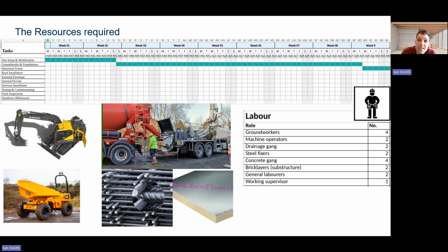The second resource is our concrete and reinforcement materials, as we can see illustrated here. These materials are required immediately after excavation and formwork, which will fall somewhere in the week 5 to 7 period. They must be delivered just in time and placed close to the pour location to minimise manual handling and avoid double handling on site.